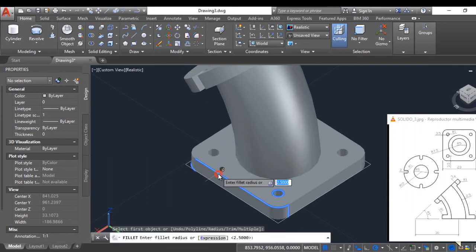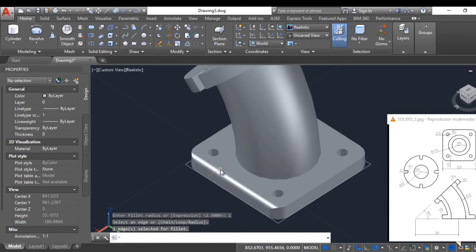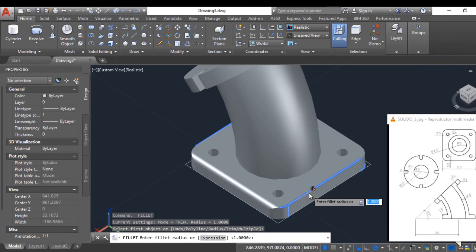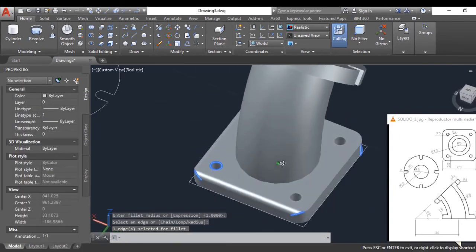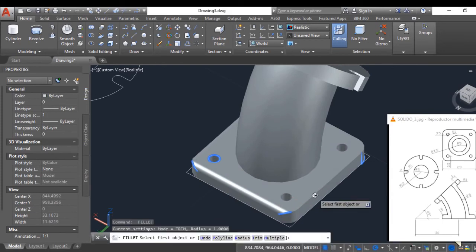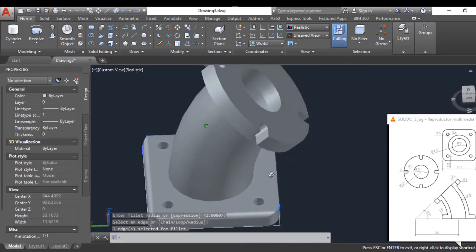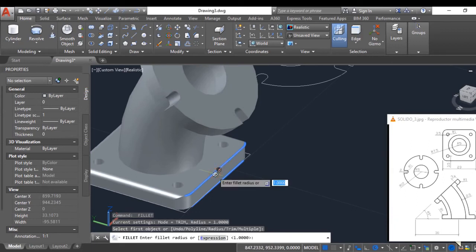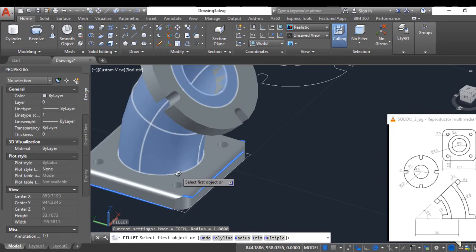And now also the beveling of this part here, I'm going to give it the value of 1. This radius, I press enter, that's it, here too. 1 of radius, I press 2 times enter, that's it. Also these bevels, 1 of radius, and I press enter twice. Here also a radius 1, I press enter twice. I'm also going to do the beveling here.